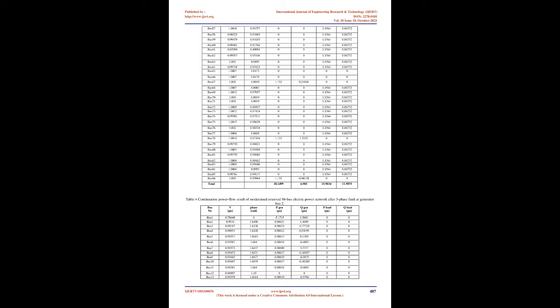The introduction of the additional equation specifying xk makes the Jacobian non-singular at the critical point and allows the computation of power flow solutions even beyond the critical point, i.e., in the lower portion of the PV curve. The tangent component of λ is positive for the upper portion of the PV curve, is 0 at the critical point, and is negative beyond the critical point.